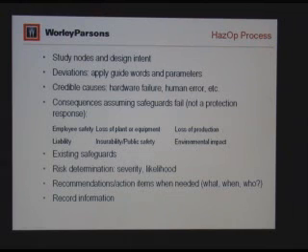So now we're going to talk about the HAZOP process. The process starts with first having the P&IDs and PFDs, and the facilitator and the team members are supposed to understand the process, and then separate the process into study nodes, because we know how big our drawings can be. There's like 20, 30 pages easily, and there's no way to analyze everything at the same time. So you need to separate it into different study nodes of reasonable size, so people can talk about the area in detail.